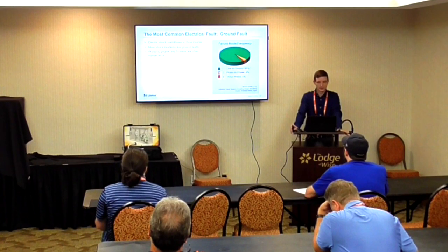3-phase is typically going to be your bolted faults and will typically be caught well before startup. But phase to phase is often an escalation of line to ground, especially in ungrounded systems. So if you have an ungrounded system and you lose one of your phases, your voltage is going to rise on your other phases, and that's going to cause an insulation breakdown or chattering or things like that, and that's going to escalate over to a phase-to-phase fault.